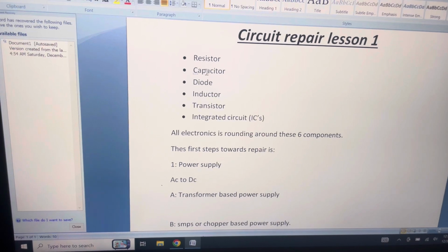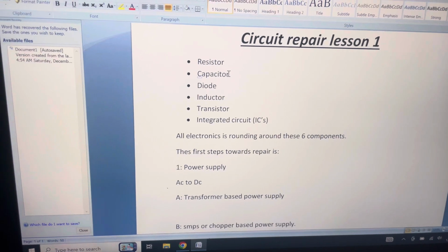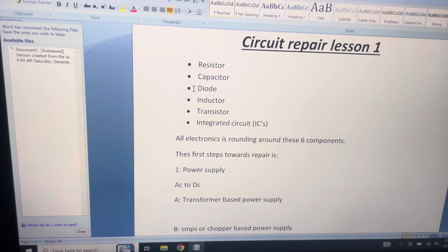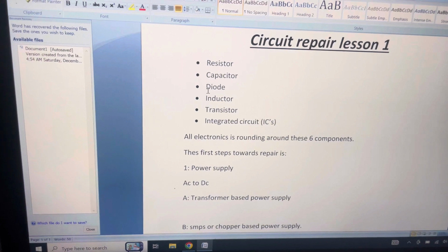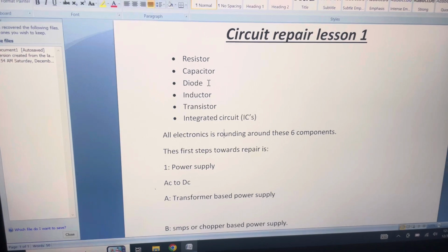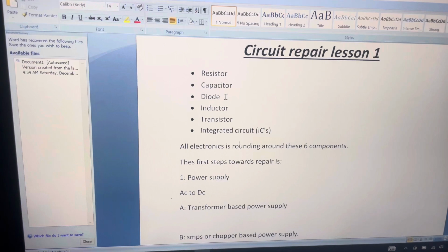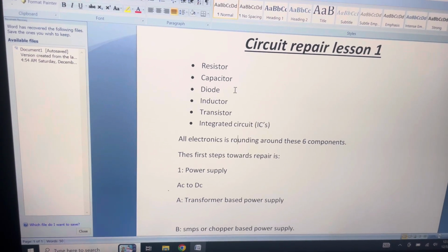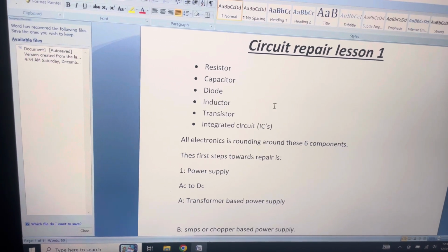If we talk about the capacitor, it is used basically as a tank. It is used for giving a steady supply to the load. If we talk about direction, then diodes are used. A simple diode is used for controlling the direction of the current. And the Zener diode is used as a regulator for drawing a specific voltage at a particular point.